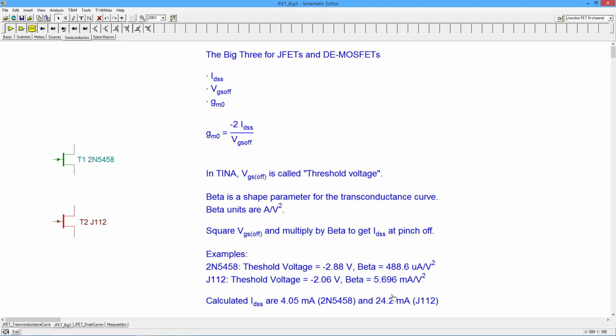Now you could take those two values and you can plug them into this formula and get a GM0 value. Now that you have GM0, you could go and, let's say, do a self-bias because you need a parameter GM0 times RS, right? The DC source biasing resistor. So you could use a self-bias graph. And obviously, you could use the GM0 to find the GM of the transistor, which we're going to need to find things like voltage gain. All right. So are we done with the simulator?